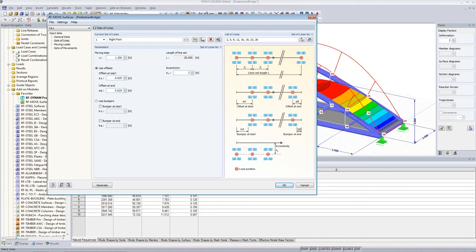So I say that my right foot is 1.1 meter from these lines we've just selected, and I have to apply a minus here. This is something you have to try. It depends on the direction of your lines. And my lines are going away from node 20, so that's why I apply a minus here. So this is the right foot.